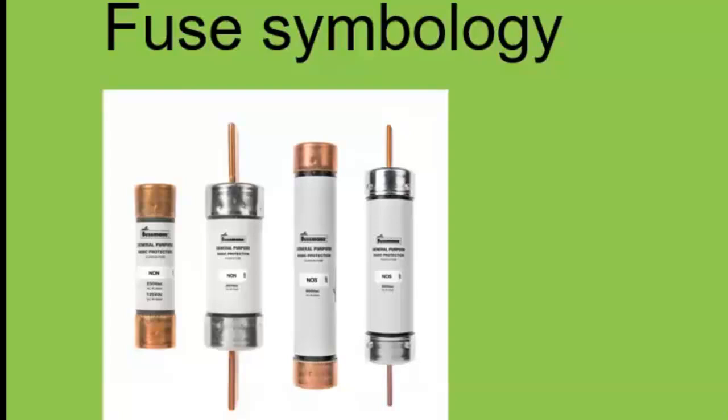That fusing element is made of resistive material. So the wire in the fusing element is made of resistive material. Once it carries load, because of the I squared R effect, definitely heat will be generated. As this heat is generated, of course, it will get to a stage where it will cause the fusing of that element and, of course, open the circuit.